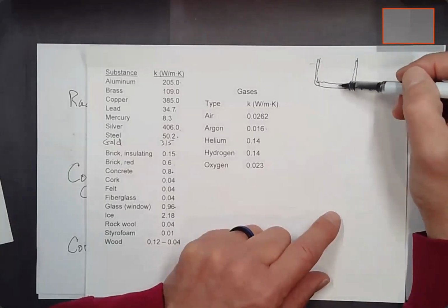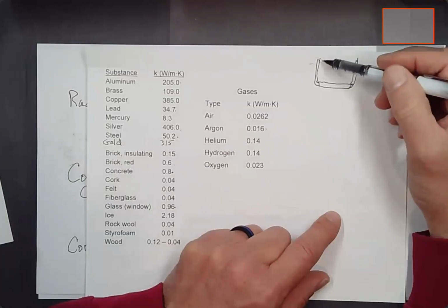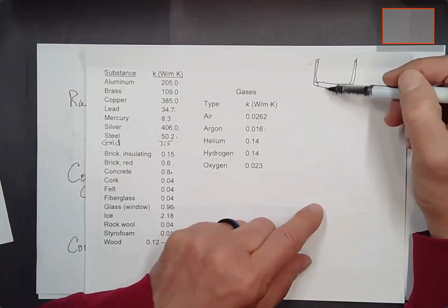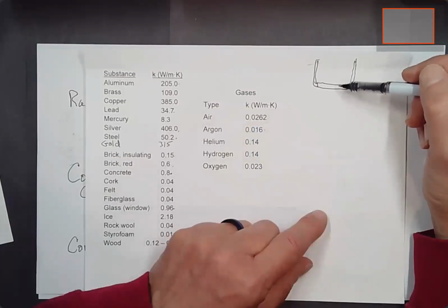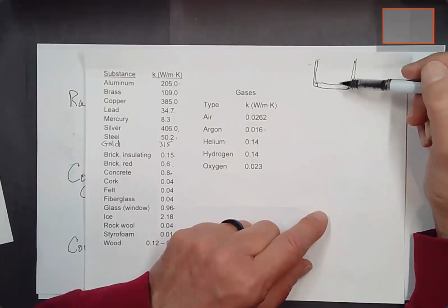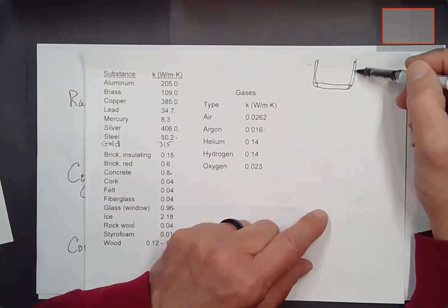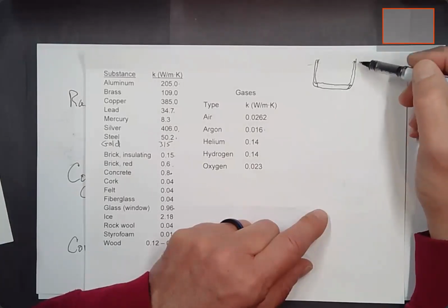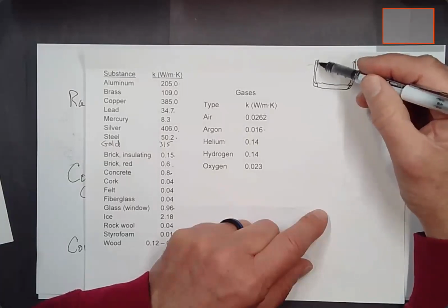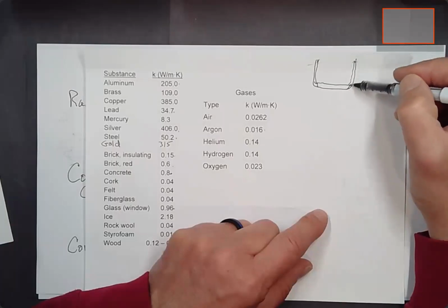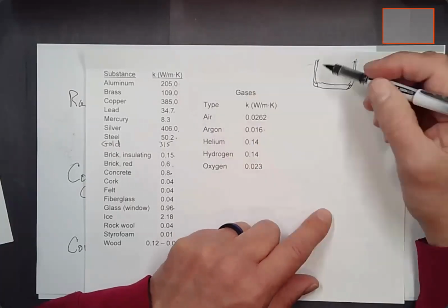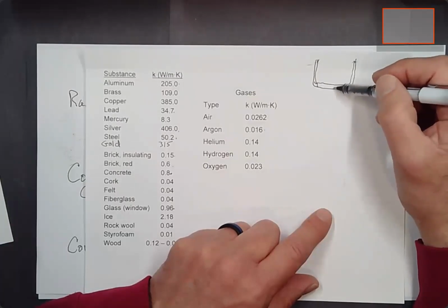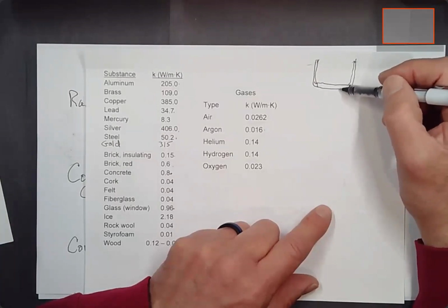Here's a kind of an outline of a pan, and something you might have in cheap pans, they might just be a thin steel layer on the bottom, or even a thin aluminum layer for really cheap pans. They conduct heat well, but aluminum oxidizes. It isn't real sturdy like steel is. So a better way is to have a layer of steel. Stainless steel is nice on the inside of the pan and the outside of the pan. And then sandwiched between those layers of steel, have some aluminum that does a pretty good job of carrying heat, but is much more affected by corrosion and oxidation and stuff like that.